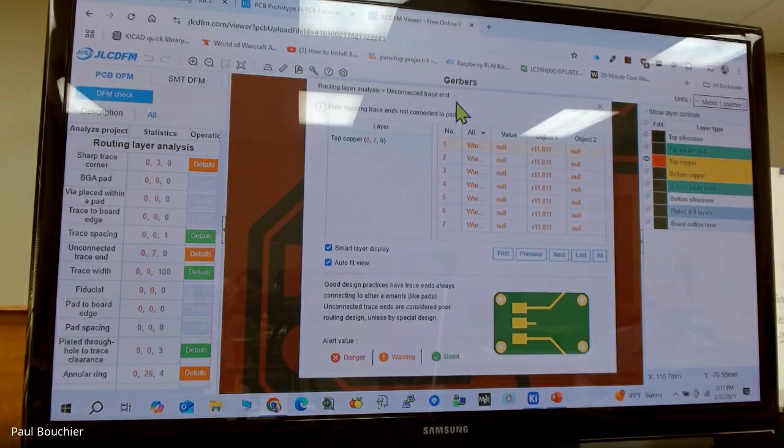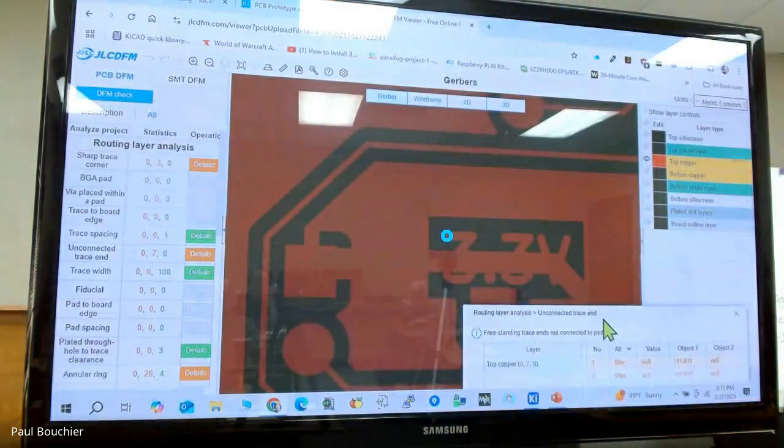So looking at the Gerber for the top trace, the 3.3 volt and 5 volt text are on copper. Okay, so there's an error. Hey, there's a good one, and you can see from the color that it's in copper. I just pulled up a single layer and it's there. So there's an error.